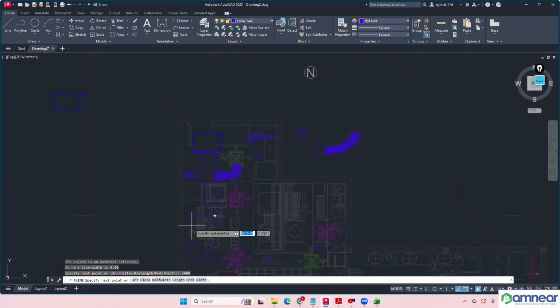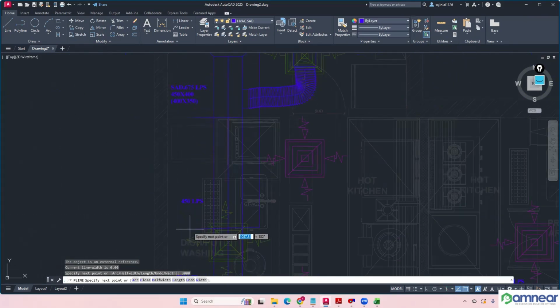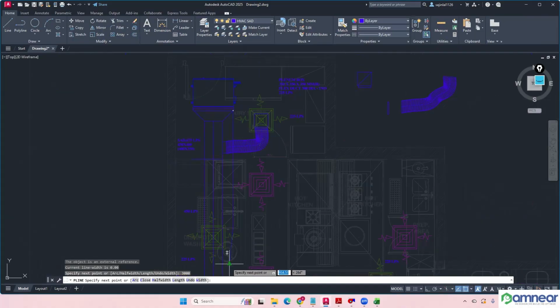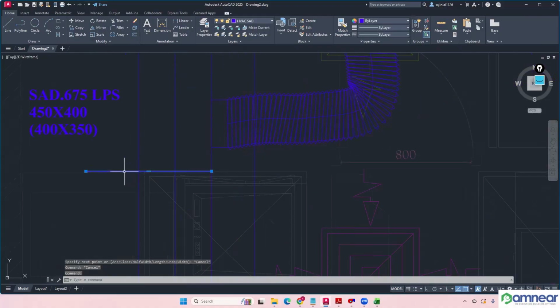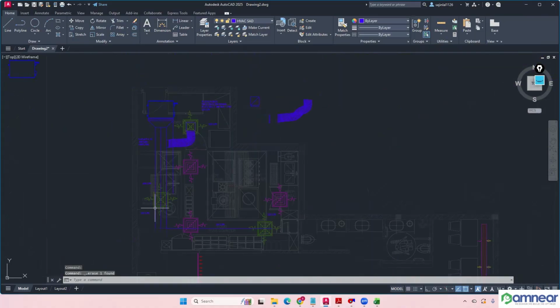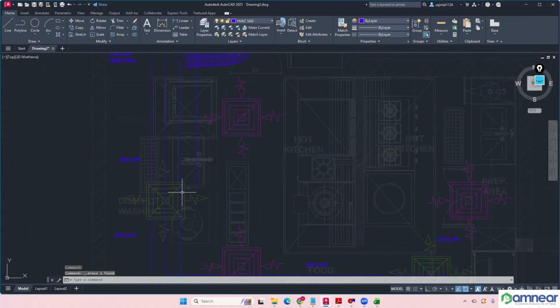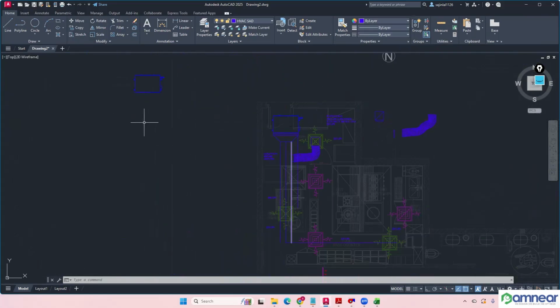It is coming here. Okay, up to here I need to maintain that duct. So better I can do one thing now. I can extend the same duct up to this diffuser. After that we can decrease it. So I'm not decreasing this duct dimension just for the acoustic insulation. After this I will be decreasing it. Okay. Anyway, this diffuser, the next size is 300 only, 300.